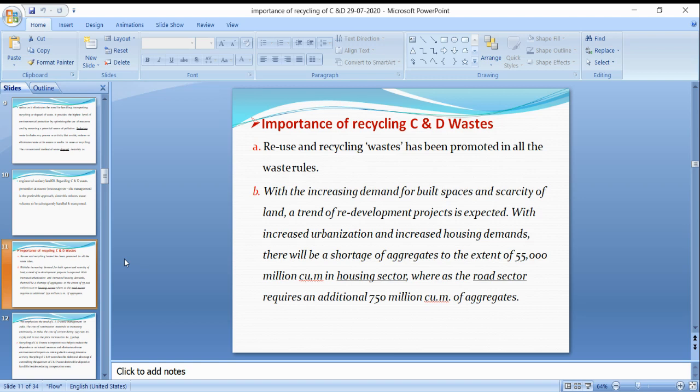After that, we have seen the example of the fine aggregate and the coarse aggregate in the concrete, and how to recycle that concrete. We have recycled the waste which comes after demolition and crushing, and that is used for pavement and also for low-lying areas where landfill is required. So like that we are reusing those aggregates, and we have seen that.